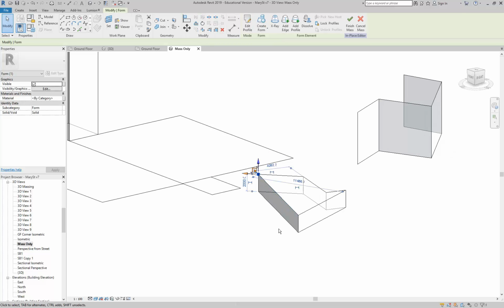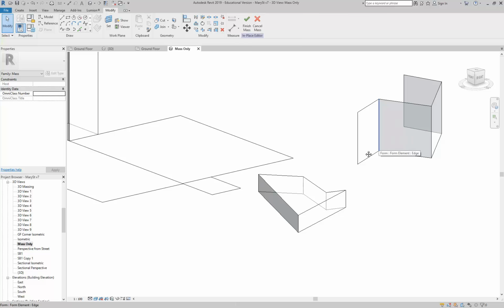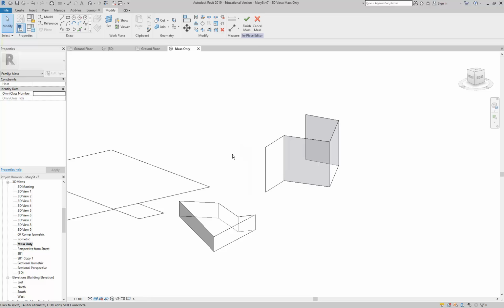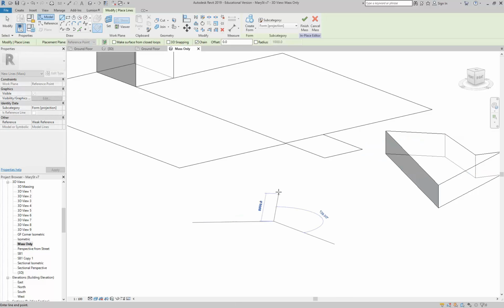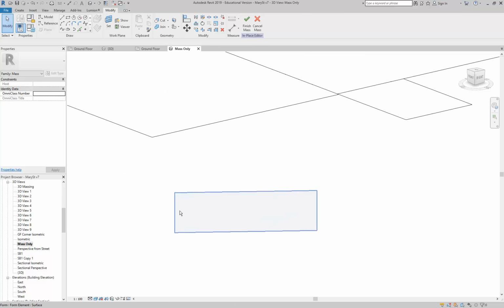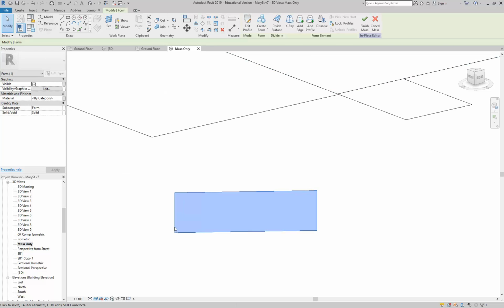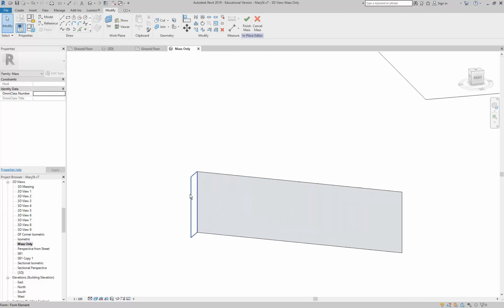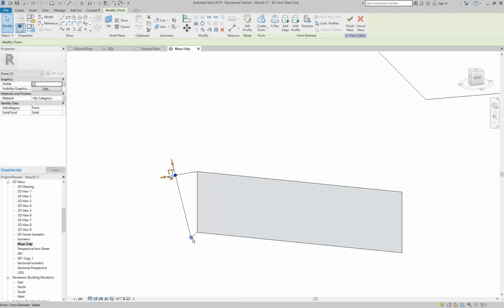But the other step is not a solid block because you didn't build it up. Exactly, that's right. But that can be a really powerful thing because sometimes you want to work with the surfaces and you can pick walls and other things. So even if you just want to do sloping walls, that can be a really good technique because if we have even just a line and create a form, then you can build on that surface and you can go forever almost. You can start creating forms from the edges of that surface and then keep building away. So it's a really powerful tool.